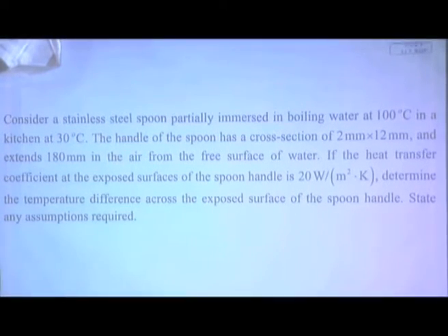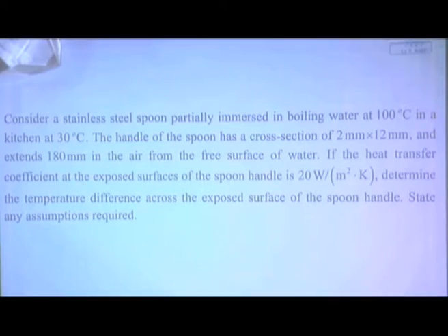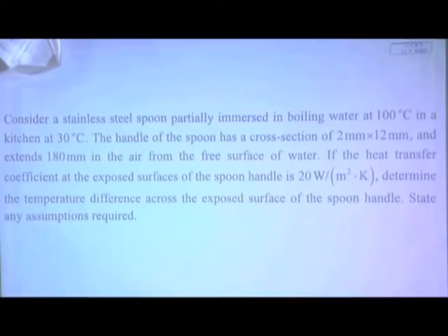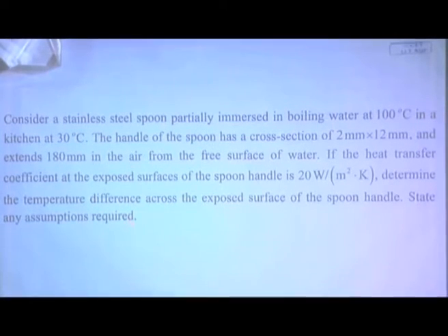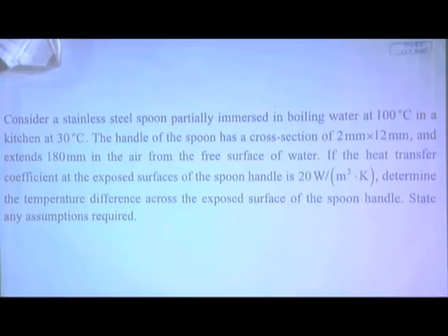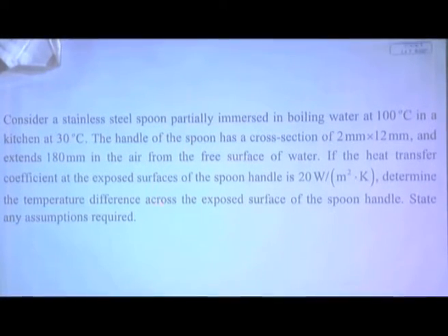Case 3. Very good. Speak loudly. Case 3. That means it is a practical case. No insulation is there. This is not infinitely long. End temperature is not given. That means there is a convective heat loss at the end. So that end, that is the fin tip, has a convective heat loss. So case 3. You will derive the equation. We have to derive the equation and use it and get it done.